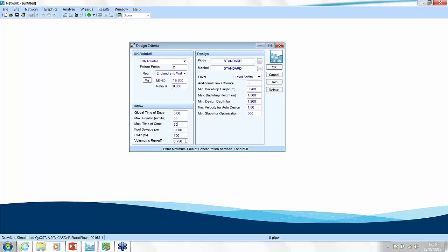These values that we use and that you see here today, these are default values, but they're not necessarily the ones that we would recommend. They've just been in the software for many years since it sort of started. We won't change them, but we do strongly recommend that you assess what this should be on an individual catchment basis. There is a groundswell of opinion that these values should perhaps be increased. In the design method that we use, the modified rational method, this 0.75 that you see here is then multiplied by a factor of 1.3. So we actually get much more than 75% runoff.